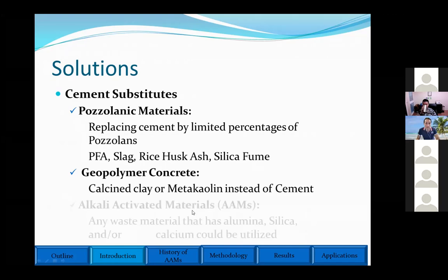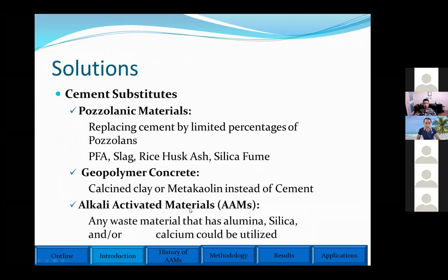The last solution is using alkali-activated materials. Scientifically, geopolymers are a subset of alkali-activated materials. For fabricating alkali-activated materials, we can consume any waste material that has alumina, silica, and calcium in it. So today I'm going to focus more on this material, alkali-activated materials, or AAMs.